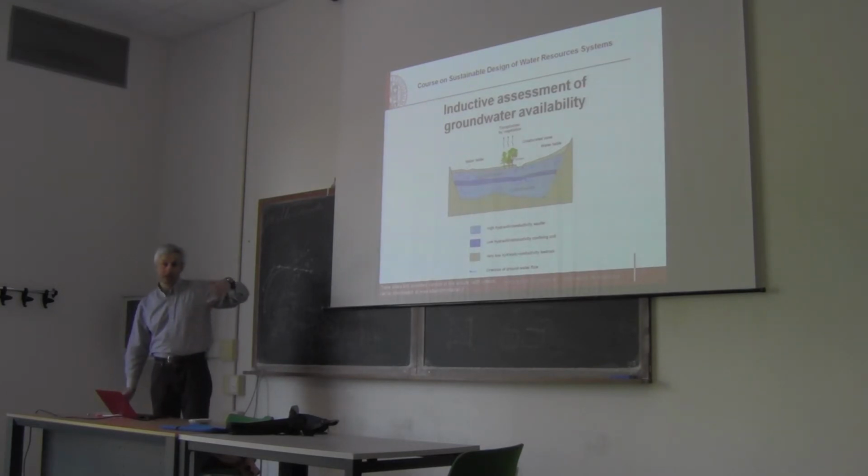What I may ask at the exam is what is a confined aquifer, what is an unconfined aquifer, and how can we estimate if withdrawal of water from an aquifer is sustainable. This is a typical question I may ask. Okay.